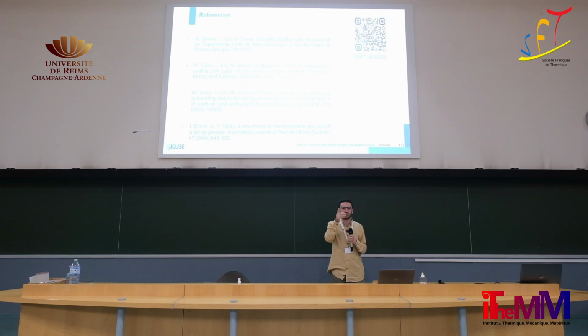Yes, there's a question here. Is the system subjected to water condensation? If yes, what are the techniques used to remove that water? Yeah, as I mentioned, there's a difference in the depth in the system, so it's not one level. It varies from 0.7 meter to 1.2 meters deep. So if there's any condensate, it will gather at the lowest point, and then we can use a pump to pump out this water.